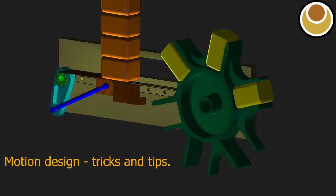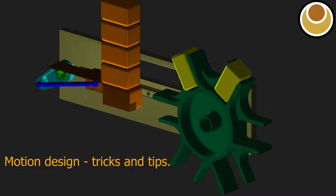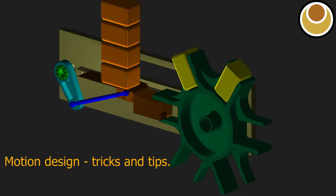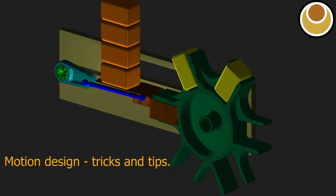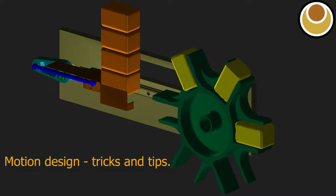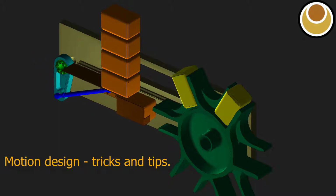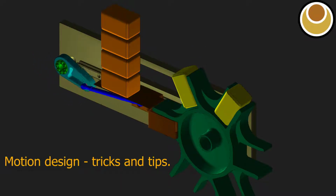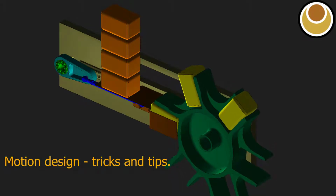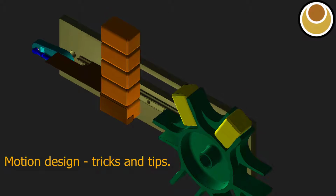I will try and illustrate these techniques using the model shown. I have already chosen the kinematic elements, parts and joints, etc., and also added some solids from SolidWorks into MechDesigner. This simple machine takes ingots from a stack and loads them into an indexing turret. Ingots are then intermittently rotated so that they are accurately presented to a series of tooling stations which perform some operation on the ingot while still. These are not shown.